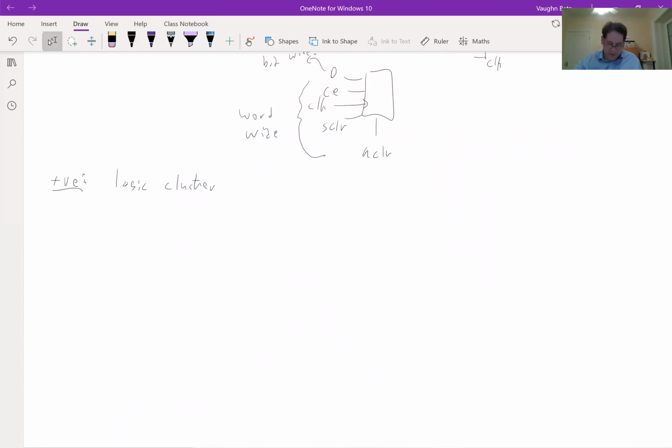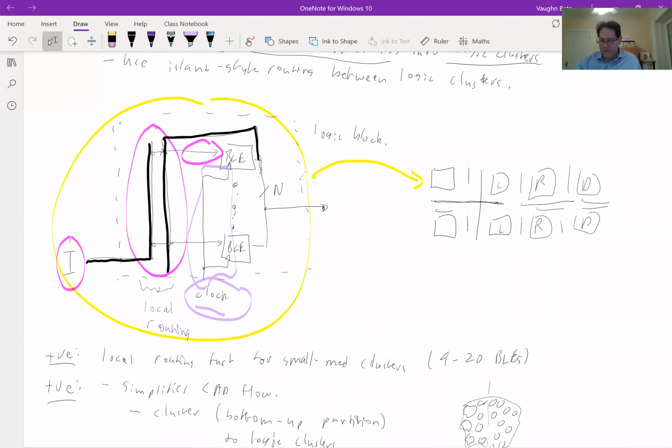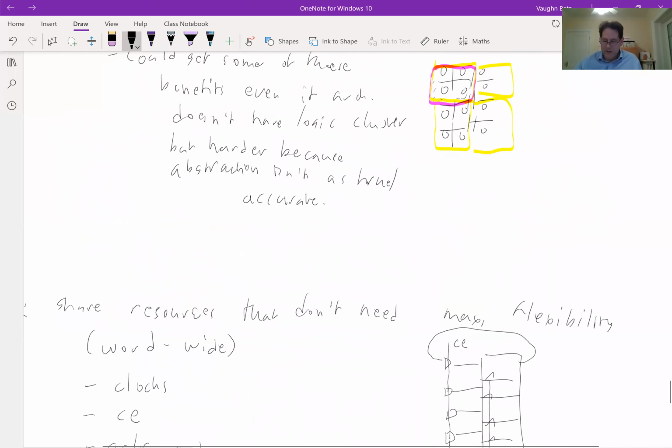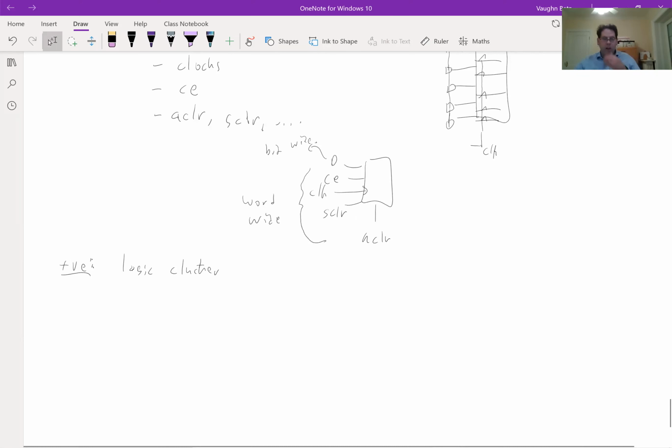Okay, and that's a lot easier to do if these blocks are more similar in size. The logic block, the RAM block, the DSP block don't have to be exactly the same size, but if they're more similar, it's easier to lay out this chip where the routing wires go across them all. They don't get bent. You don't wind up with areas with wide channels and areas with narrow channels. Everything just works out better.